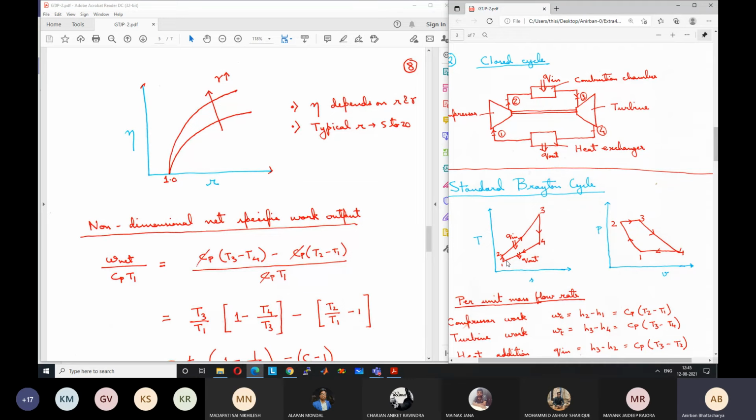But here it is unavoidable because you have only gaseous product, right? You only have gas. In case of the steam turbine cycle, we had water which can be condensed, and because it can be converted to liquid, we could increase the pressure in the liquid state using very little energy.